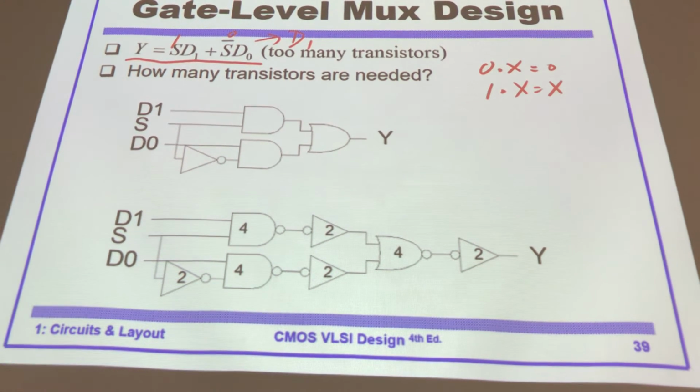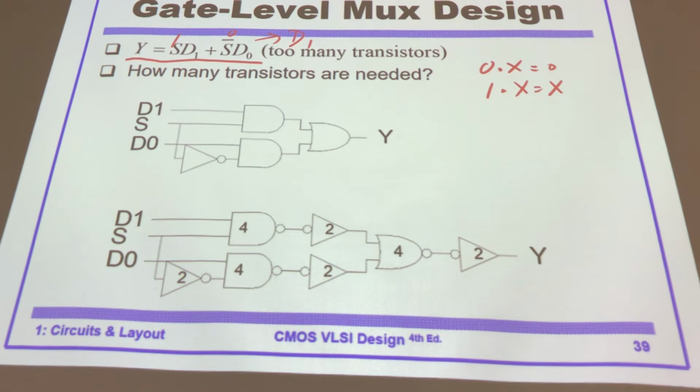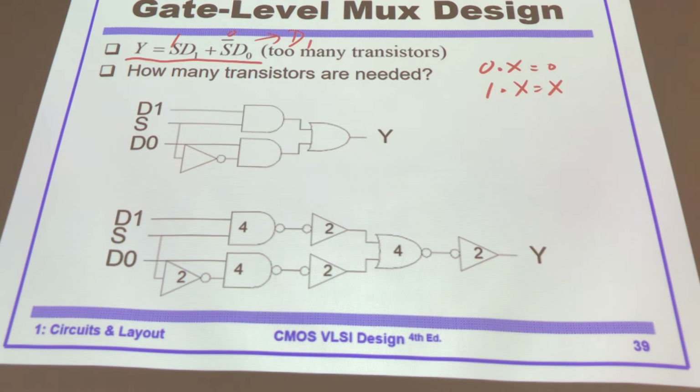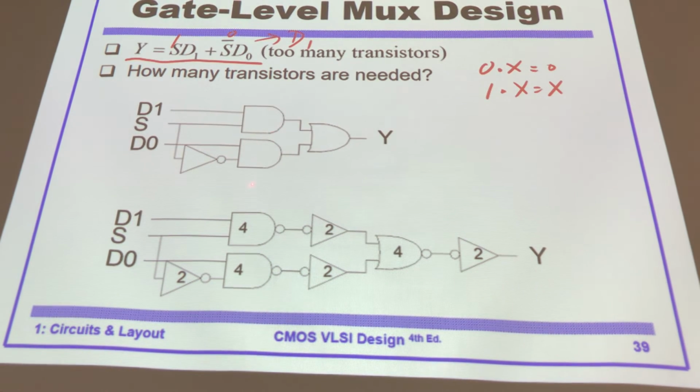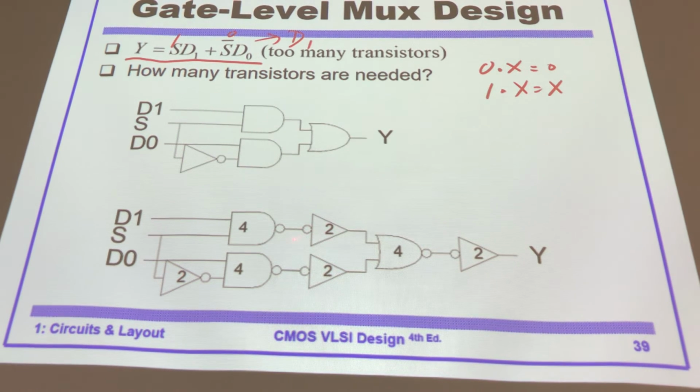So totally, that's quite a lot of transistors. That's going to be 20, right? Yeah, 20 transistors. But before that, why are these two equivalent? Like I said before, an AND gate actually is built from a NAND gate cascaded with an inverter, right?